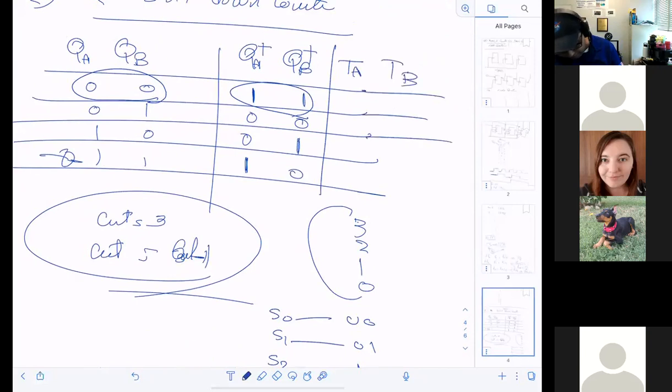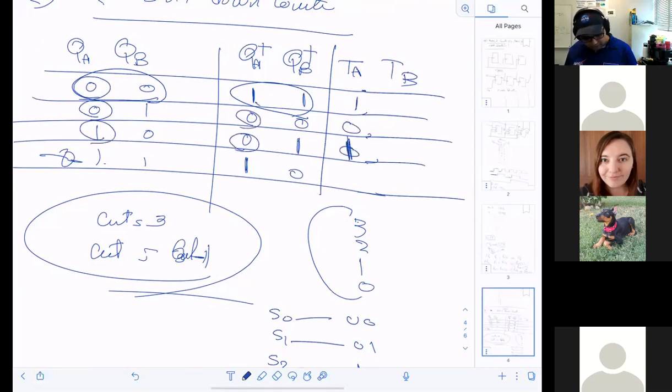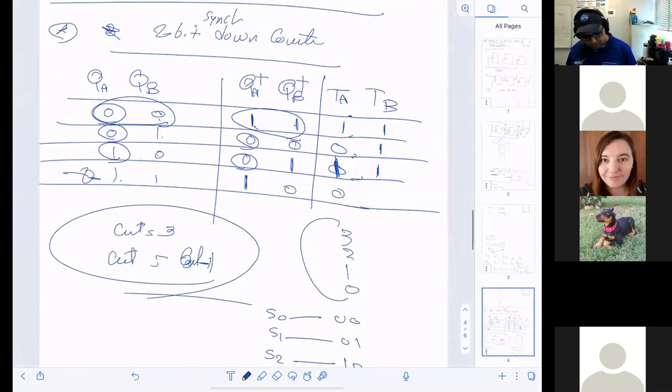And as I remember from our discussion, that's an XOR, right? So this is 0, 1, it's gonna be 1. This is 0, 0, they're gonna be 0. This is 1 with 0, they're gonna be 1. This is 1 and 1, it's gonna be 0. This is 0 and 1, it's gonna be 1. This is 1 and 0, gonna be 1. This is 0 and 1, it's gonna be 1. This is 1 and 0, gonna be 1, and we'll be done.